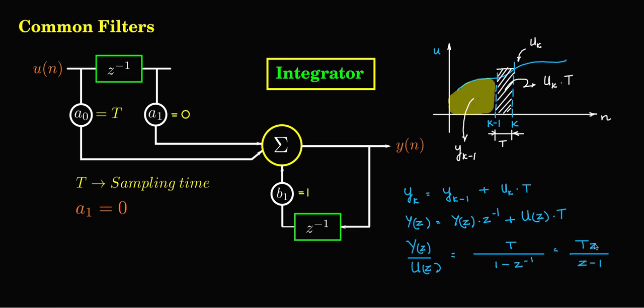The zero is at z is equal to 0, or it could be at many places. In fact, the calculation of this delta area is where different algorithms come from. So I could take this point uk minus 1, draw a straight line and take that rectangle. So uk minus 1, go forward, take that rectangle. That's called the forward Euler's rule. So uk minus 1 into t, that is also one possibility.